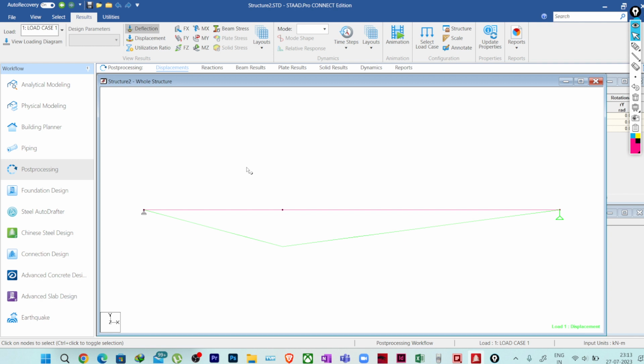So if the beam is bending like this, this face is tension, the top face is compression, correct? That means the bending is happening downwards, so I will be giving tension reinforcement. When I will be designing the beam, I will be giving tension reinforcement at the bottom, compression reinforcement at the top if required, correct? If not required, then I will not provide, because concrete itself will take the compression.